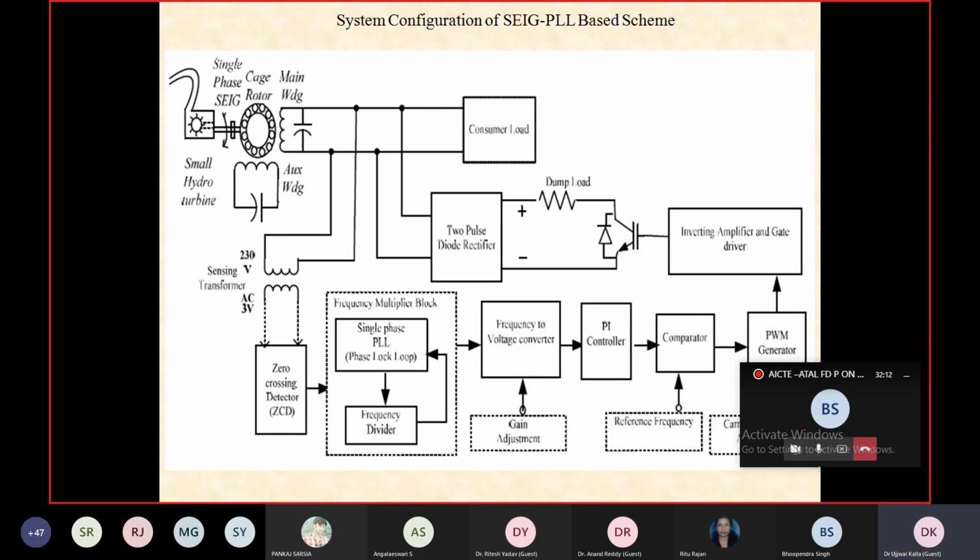And even if it is required, try to have a capacitor of the minimum possible value, just enough to get the work done. A large value capacitor should never be used. The larger the value of the capacitor, the poorer the power factor will become, and that will inject more harmonic current into the system. So if you want to improve the power quality of your system, you should try to reduce the values of the capacitors connected in the output of the diode rectifier.